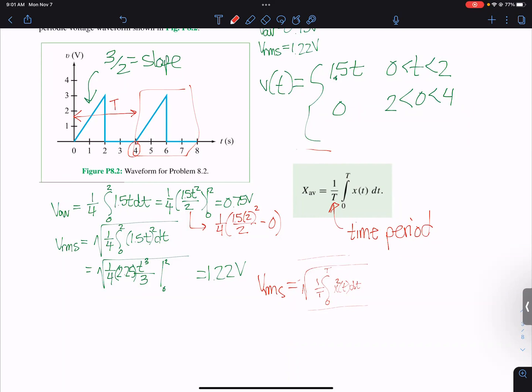I want to know what components, so I'm going to fight all the parasitics that come out because I plugged that in. The cord of the plug itself has a parasitic resistance and capacitance, and even a little bit of inductance. Because there are physical things there, that's going to give you some noise, and then you want to offset that. And so this is why we're looking at that.